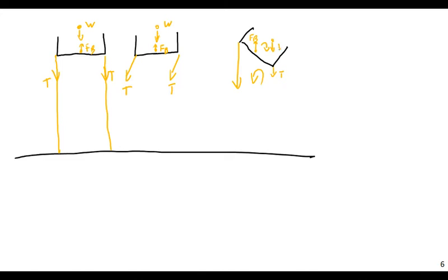So this is just sort of a hack, you might say, to get around the problem that a floating hull, at least for an oil platform type design, is often intrinsically unstable. Now, yes, you could counter this by putting a lot of dense ballast material at the base of your tank.